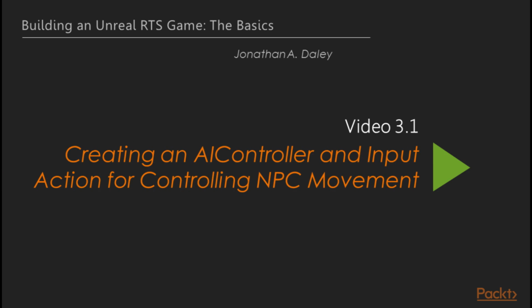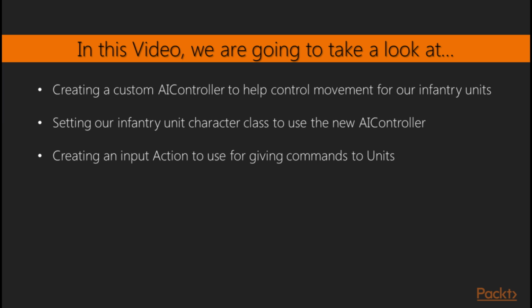Video 3.1, Creating an AI controller and input action for controlling NPC movement. In this video, we're going to take a look at creating a custom AI controller to help control movement for our infantry units. Then we'll set our infantry unit character class to use the new AI controller. And finally, we'll create an input action to use for giving commands to units.